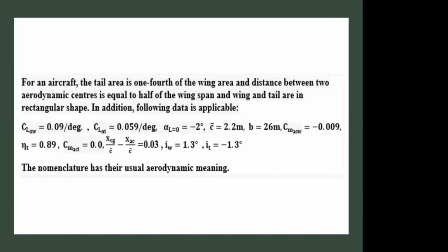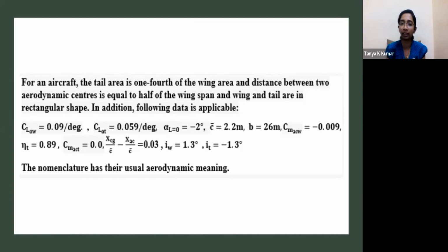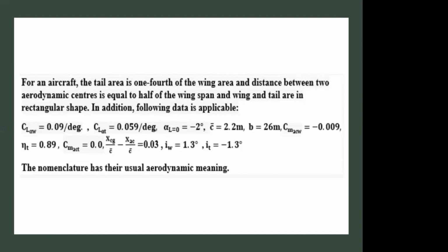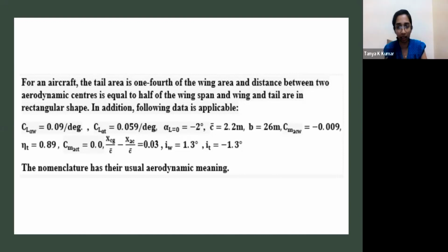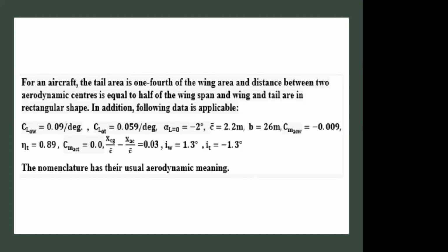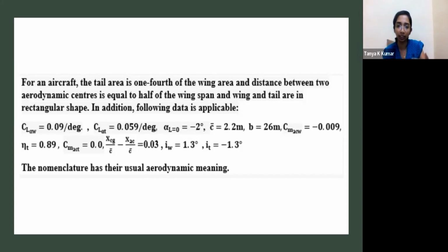For this question, geometrically similar aircraft, if the aircraft has larger mass, it's harder to disturb the aircraft from the position of stability, right? That is the explanation. No, but if it's bigger, the mass will also be in proportion to the bigger one. Yeah, so if it is heavier, it is harder to deviate the aircraft.